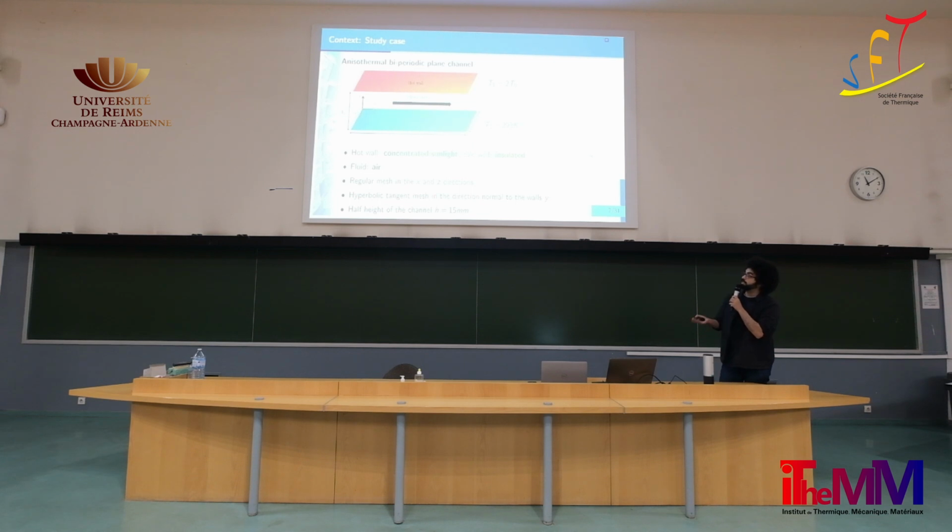The way we simulate what happens inside our solar receiver is extremely simple. This is the simplest modeling case. It is a biperiodic plane channel flow with 2 periodic directions, the direction of the flow and the spanwise direction. The wall normal direction represents the asymmetrical heating inside the solar receiver. The hot wall represents the wall that is subject to the concentrated sunlight, and the cold wall represents the insulated side of the receiver.